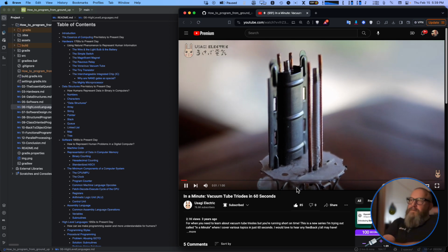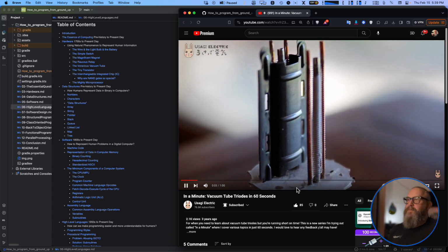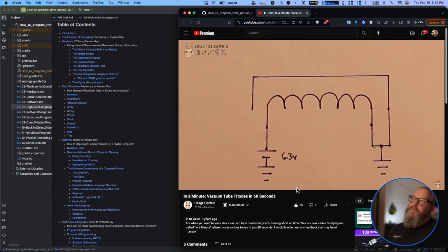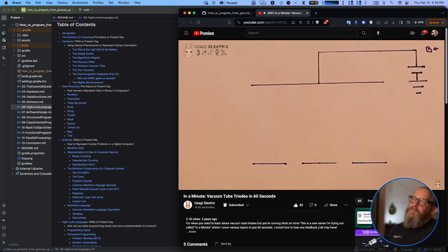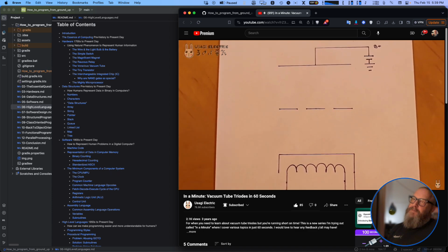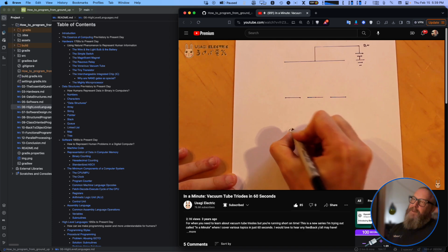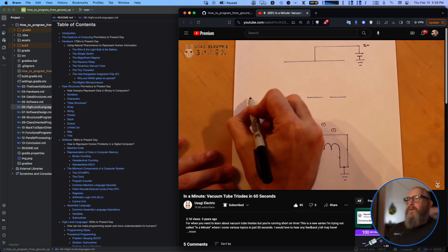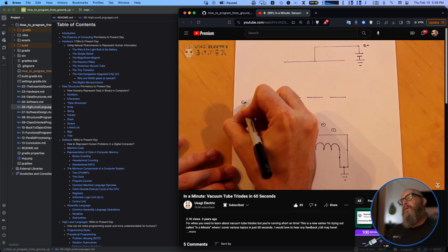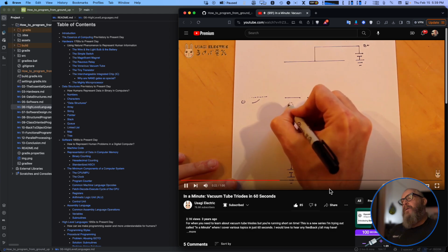The triode's construction is very similar to an indirectly heated diode. There is a filament that heats up a negatively charged cathode, and there is a positively charged plate. The triode features one additional element in between the cathode and the plate, the grid. The hot cathode emits electrons, which are attracted to the plate, but the flow of electrons to the plate can be controlled by the charge on the grid. If the grid has a sufficiently negative charge...